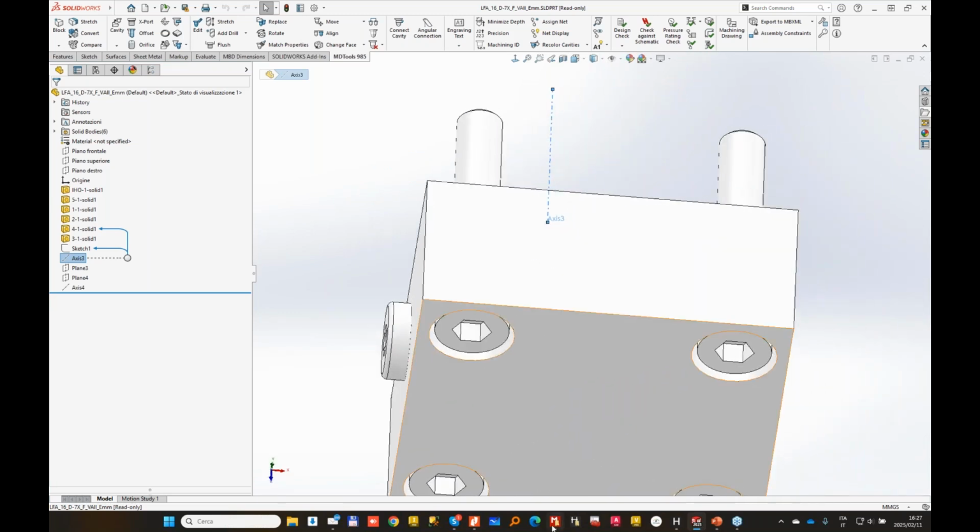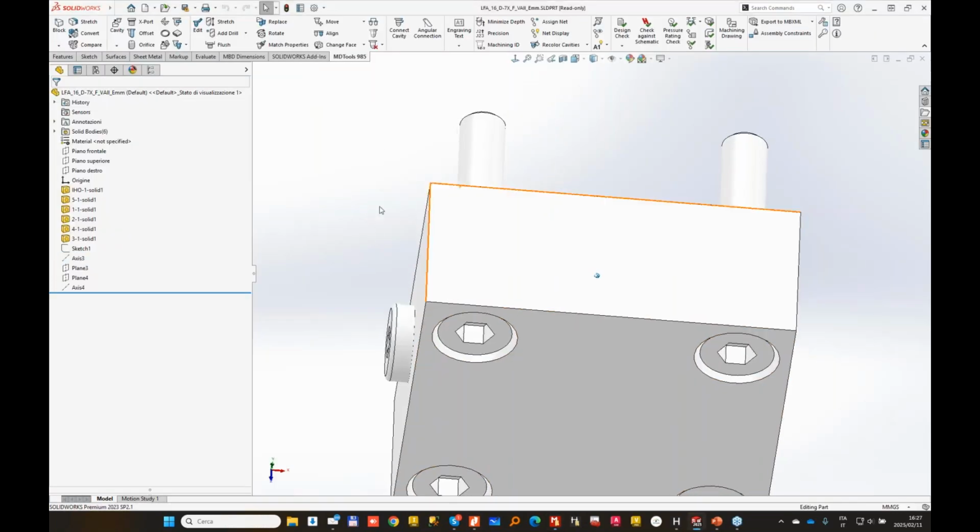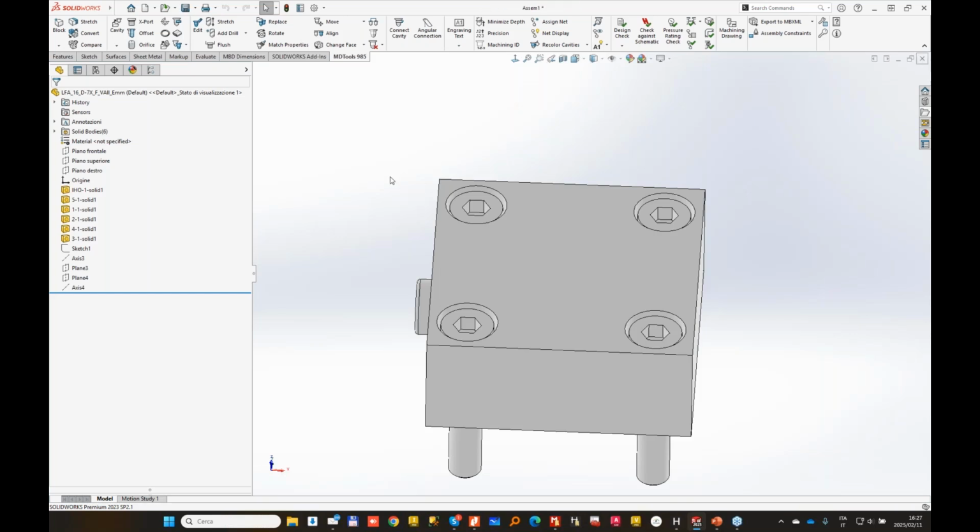It's up to you. You can use the locating pin and BH1, but my recommendation, if you want to instruct a component, always use BH1 and BH2, nothing else. Because if you use a locating pin, it will be much more complicated to have good precision for assembly. So that's a change in the assembly environment.